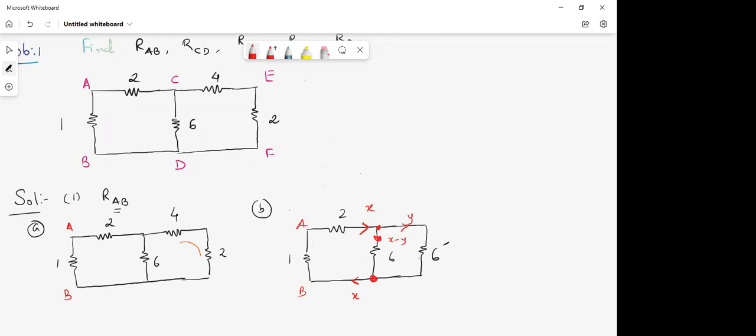So listen, now you can easily identify a parallel combination. Let there be a current. It must be divided after passing through the components, and it must be reunited back to give you the same value of current which was there before division. If these steps are fulfilled, then only you will say that the resistors or components given are in parallel. Understood? Understand this carefully, otherwise there can be problems.